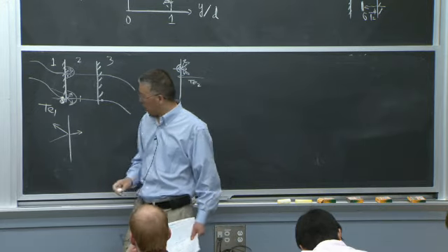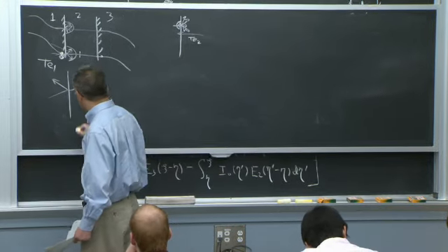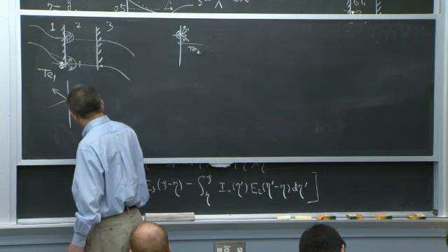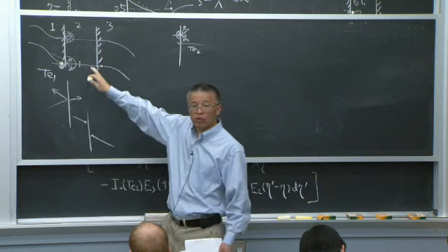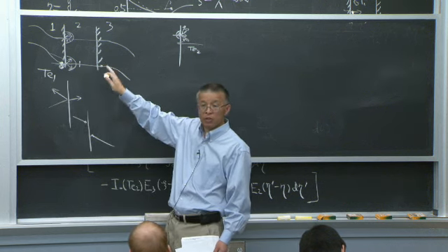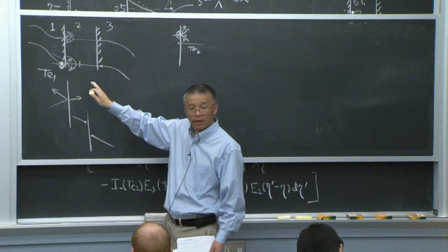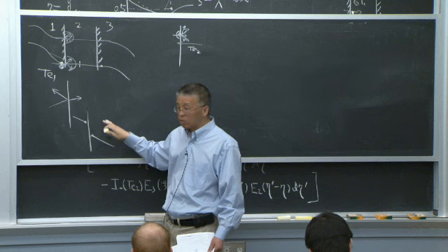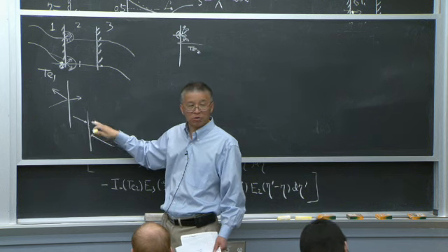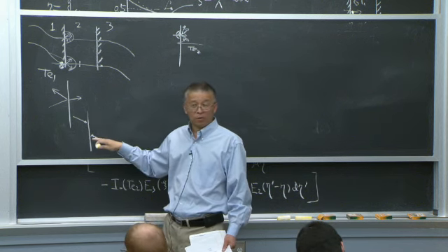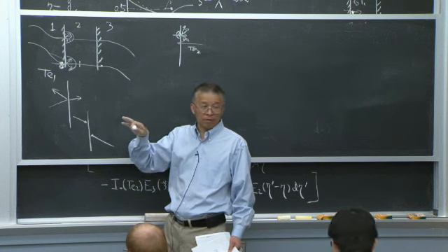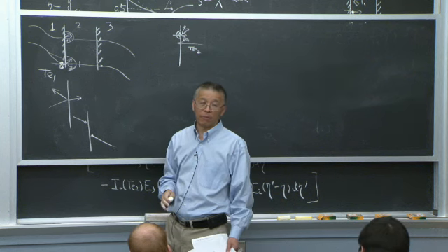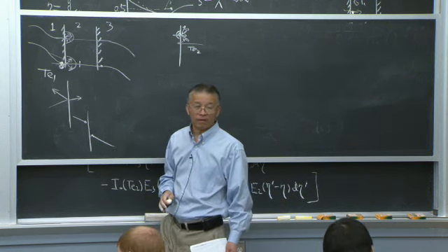And this is where you actually have a physical temperature discontinuity at the two interfaces. And if you do the Boltzmann equation, you can consistently include everything. Okay? And in chapter 5, I discussed this. It's really about how careful you have to be in defining temperature when you go to this ballistic or quasi-ballistic regime. Otherwise, you may be comparing apples and oranges. Okay?